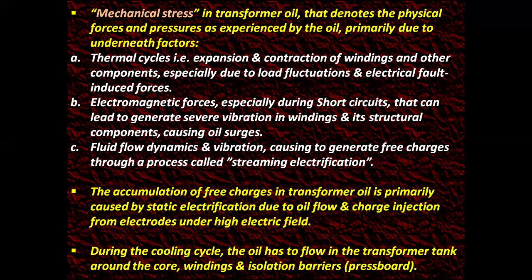B, electromagnetic forces, especially during short circuits, that can generate severe vibration in windings and structural components, causing oil surges. And C, fluid flow dynamics and vibration, causing generation of free charges through a process called streaming electrification.